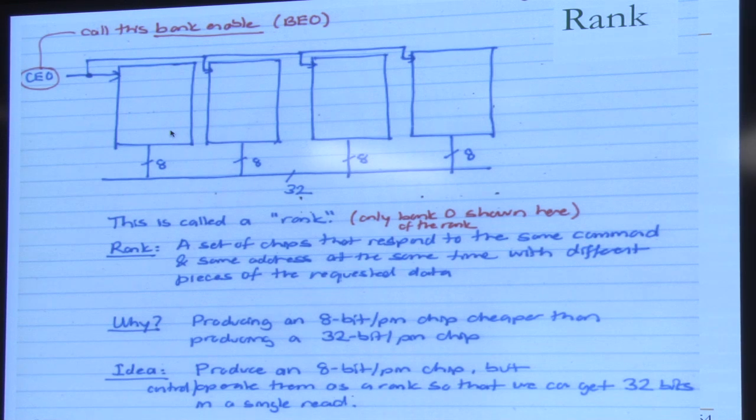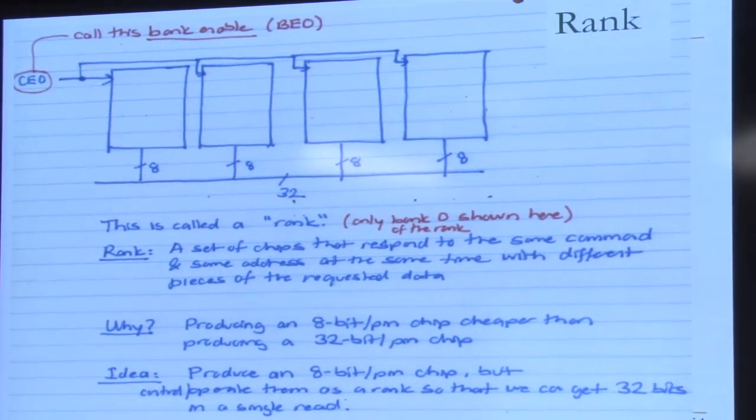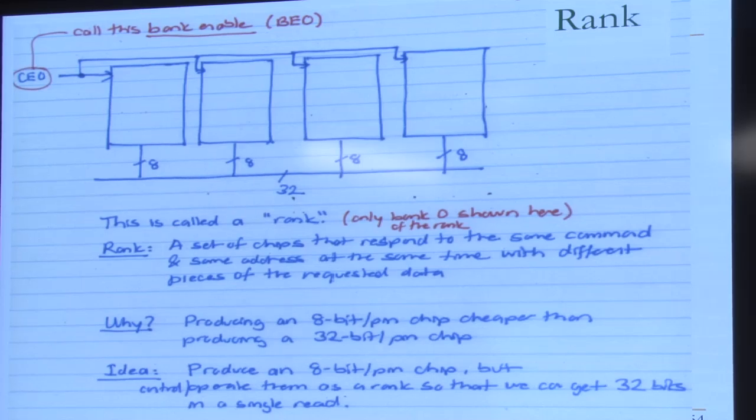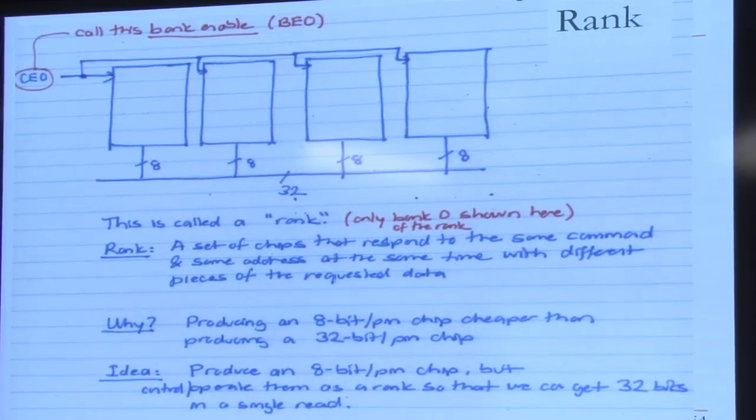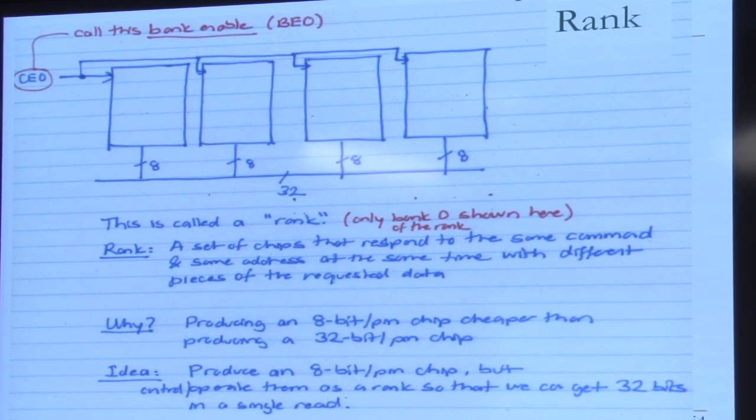Yes? So you have 4 of them. That's right. But each chip is hopefully much cheaper, more than 4 times cheaper. That's right, yes. So why stop there? Yeah, you could. So there's a trade-off point, obviously, right? You can talk with the DRAM manufacturer. Why stop there is a really good question. And how does this affect the entire system cost, right? That's also debatable, right? But DRAM is optimized this way today because pins are limited.